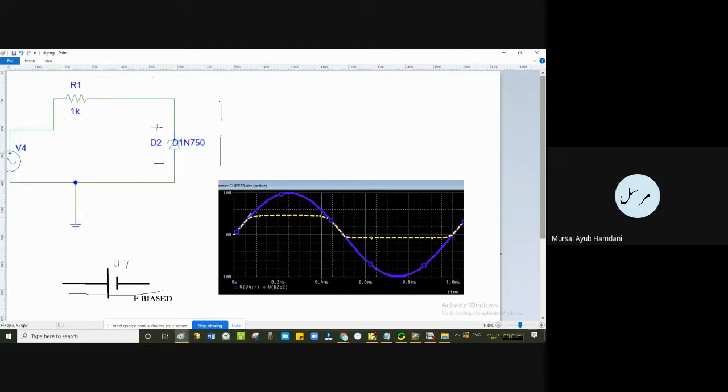However, as the input goes higher than 5 volts, this will simply act as a voltage, so a constant voltage of Vz, that is 5 volts. So throughout this time, it will be at that particular value. However, when the values of the input go below 5 volts, it again goes into the classical reverse bias mode, and it will be open circuit. Open circuit here in the shunt connection will mean output follows the input, so it goes like this.